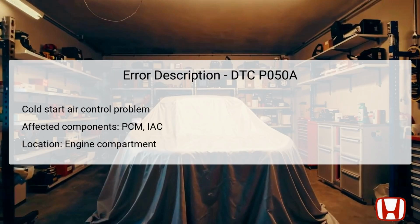The DTC P050A signifies a cold start idle air control system performance problem. This code indicates that the powertrain control module, PCM, has detected a discrepancy between the actual intake air amount and the specified or target intake air amount. The PCM is integral as it analyzes various sensor data and controls engine functions, particularly the idle air control valve, IAC. The IAC is responsible for regulating the amount of air entering the engine during idle conditions, especially when the